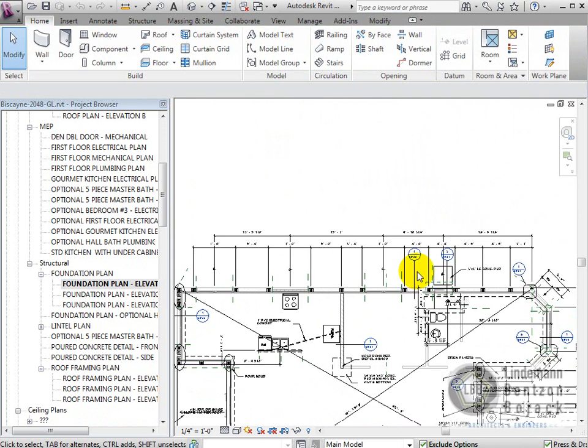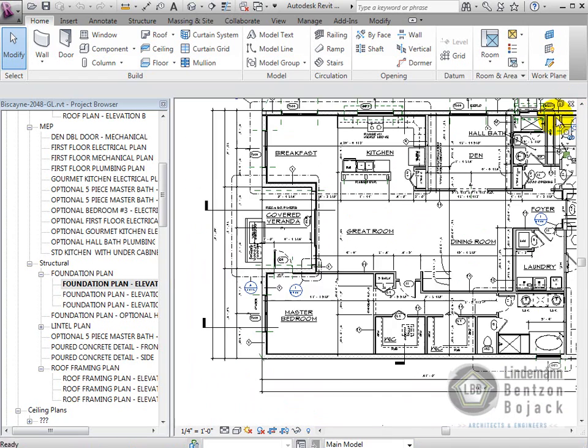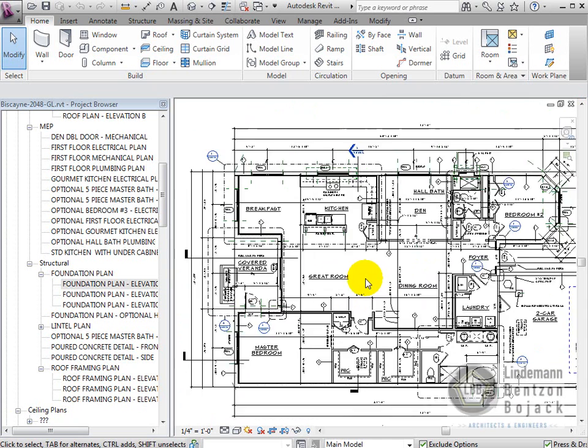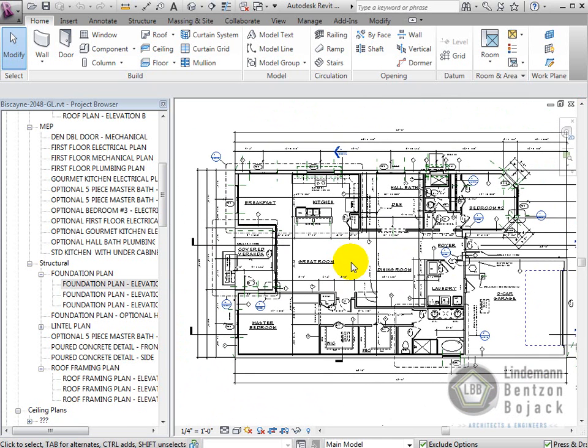So what I recommend when you need to make a garage left-hand version, you save your right-hand version under the left-hand name and then erase everything except those entities out of your drawing. That way you have the same views already set up.